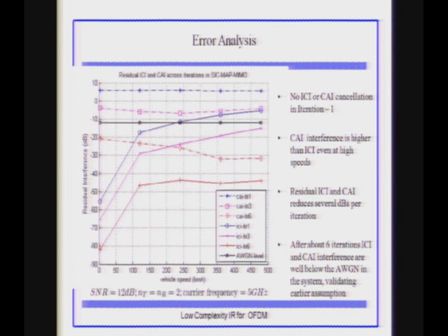Yes. And remember, it's not iterative schemes or anything, it's just simple equalizers, because of cost and power saving. When you have such a simple equalizer and these blips, due to high Doppler, the impulse synchronization is lost, and that's why you get a blip in the video. That's where it all started.